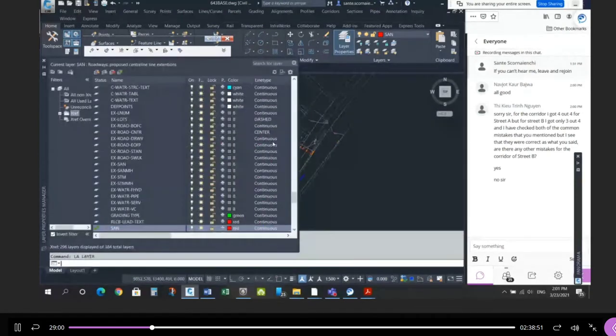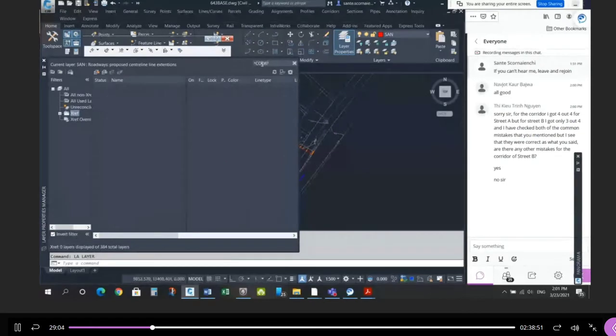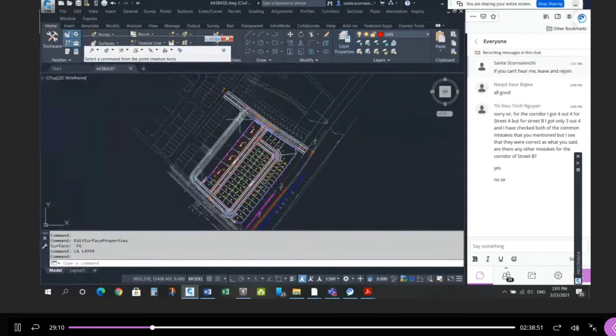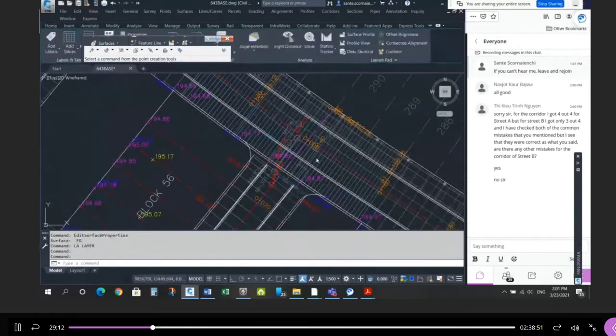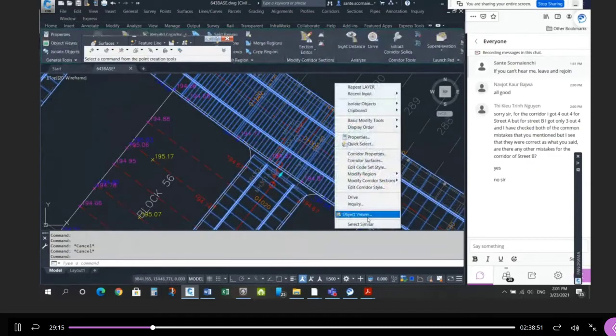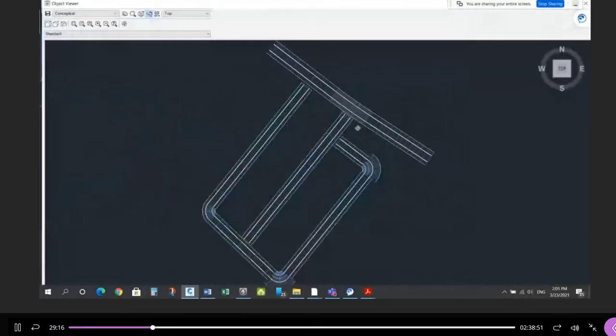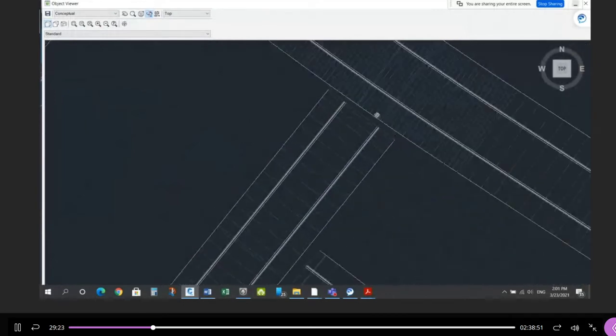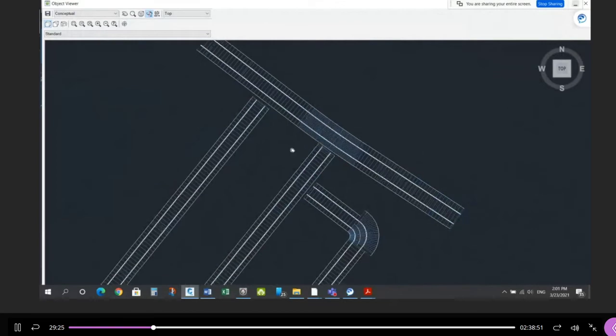Remember when you model it, I'll show you mine again. Again, these are other things I look for. So if you go to the corridor and you look at the corridor, and I mean in 3D, it helps isolate it, right? The pieces should not overlap. There should be a gap between the pieces, right? Make sure they don't overlap. That might cause a problem.